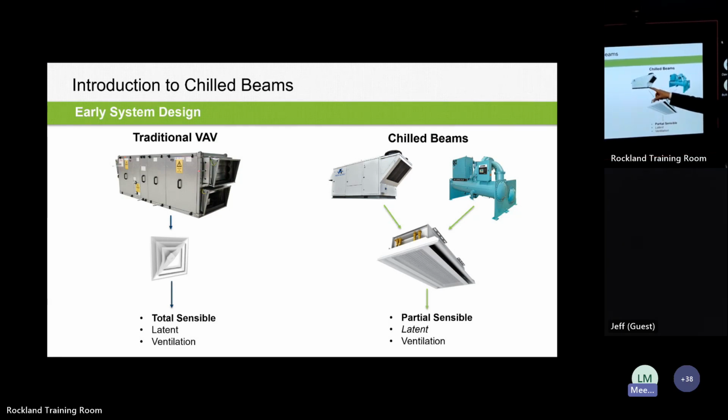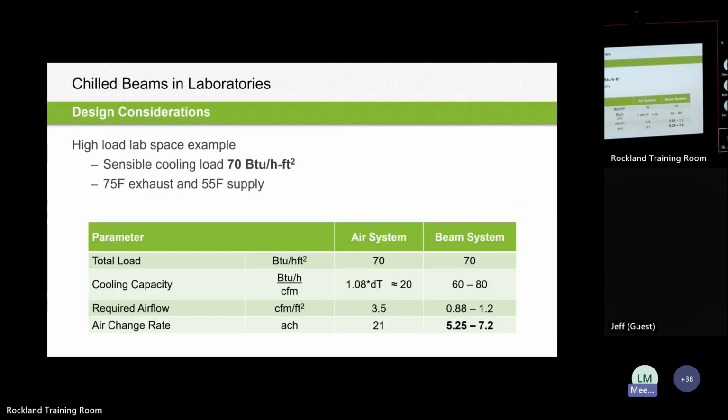If you're not using a large amount of air to bring all of your latent and sensible conditioning into a space, you've got a reduced amount of air in that latent potential. We have to make sure that we're depressing the moisture enough from the outside air coming into the space to appropriately account for the latent gain within the space. So that's a lot of what we're going to talk about.